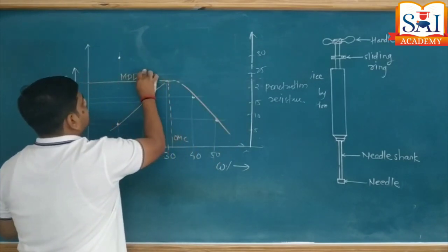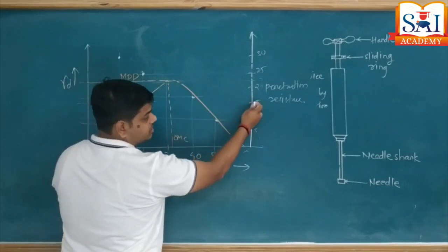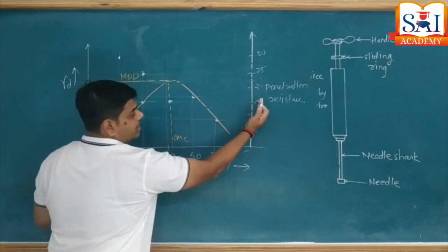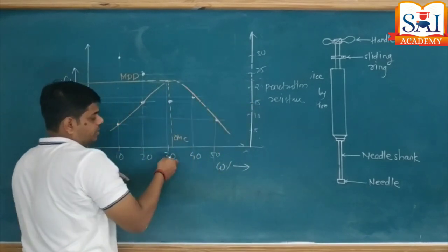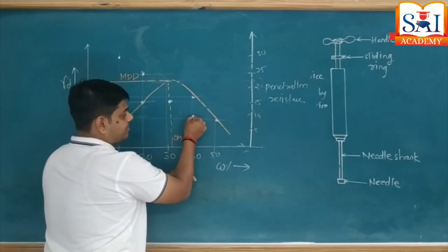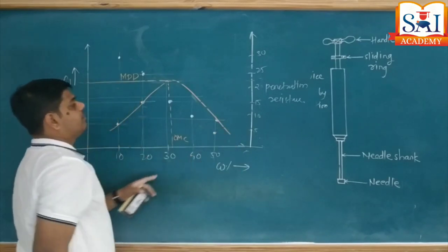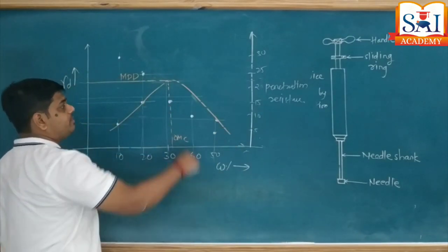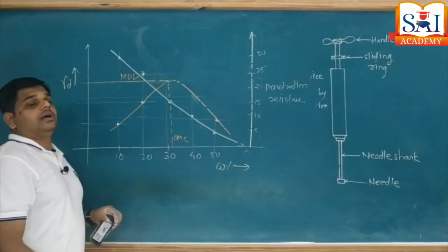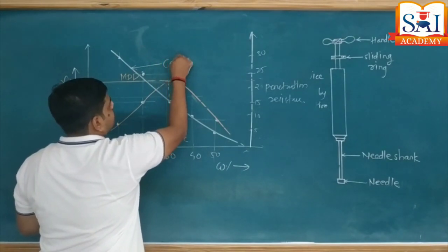Here is resistance 25. Third trial, water content 30%. Say resistance is 15. So on this axis mark 15 like this, with reference from this right side. Water content is 30%. For the fourth trial, say the resistance is 10. Mark over here. Then the last one, suppose, is 5. Now we have all these points. These points we have to join by a smooth parabolic line like this, and this line we call the calibration curve.